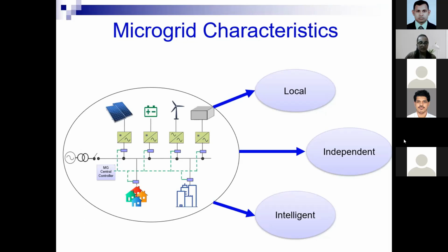Now let me give you an example. As you all know, an advanced controller in a microgrid can track real-time grid prices, for example. And if the energy prices are inexpensive at any point, it may choose to buy power from the grid to serve its customers rather than using energy from, say, its own solar panels. The microgrid solar panels could instead charge its batteries, and later in the day, when the grid power becomes expensive, the microgrid may discharge its batteries rather than using grid power.